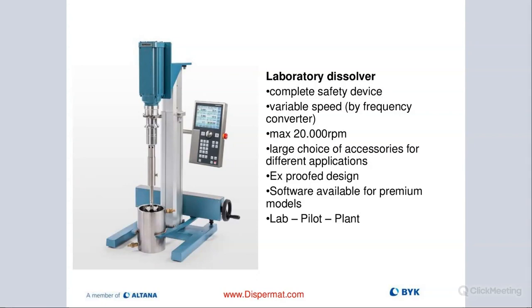So you can see that wheel on the right side that's used to loosen and tighten the container clamp and to ensure that the container is always perfectly centered and locked in place. So you can't push it out. It's important that it's perfectly centered. You don't want the blade at high speed hitting the container wall. Metal on metal, especially if you're running solvents, is not a good idea at 20,000 RPM.